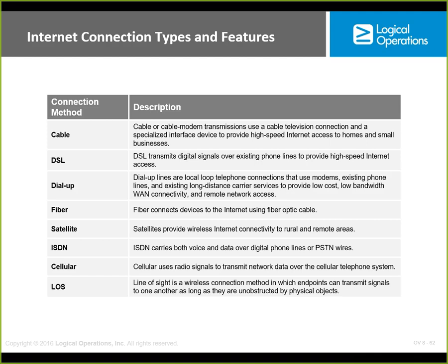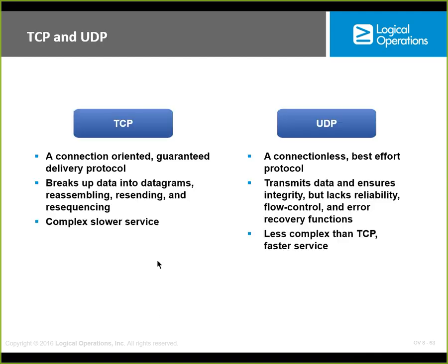He has to be able to see a particular mountaintop in order to get the signal, and they use dish antennas in order to focus it so he can get a signal. If a tree grows up in the way, you're going to have a problem. You have to be careful about objects. You have to have an unobstructed view of these things.